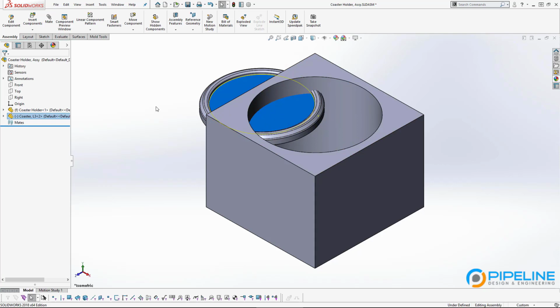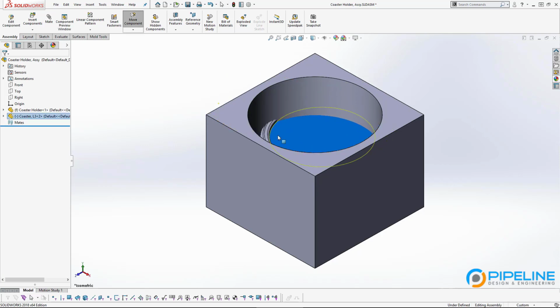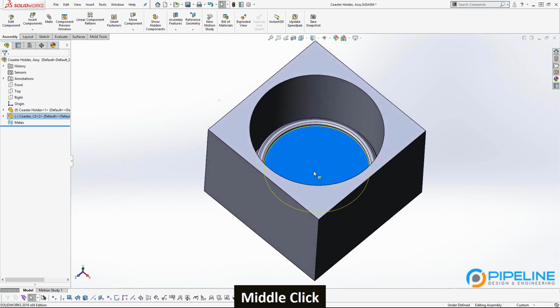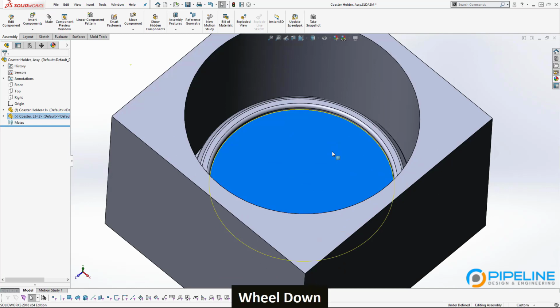The reason why this is important is because, especially in really large assemblies, if you have 200 parts and you don't have everything fully defined, let's just say you kind of just drag this in here and it looks okay, and you call that good, and then you put another 100 parts in there, you might not realize that something doesn't fit properly, or that something broke at some point.